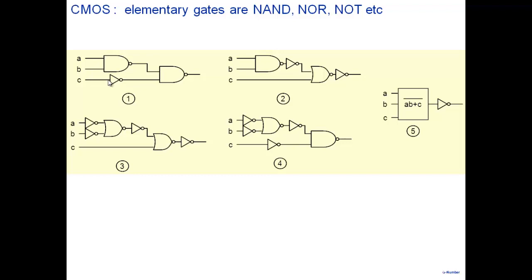Because note that at this stage, what do I have? This is just a symbol. I don't have an area here. It's just a NAND gate symbol or a 3 input gate symbol. All I have is symbols. I know that a NAND gate is probably composed of so many transistors that I can count, but area will become available only when you do the layout. Once you actually do the layout, you know how much area a particular entity occupies. This is too early a stage to comment clearly on how much area something is going to have. I don't have that particular estimate at this stage. All I can say is, comparing this, this is likely to have lesser area.